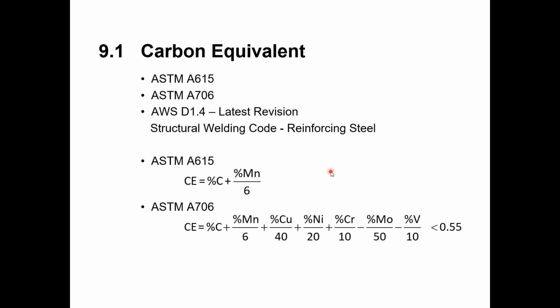All right, let's say you had a carbon equivalent of 0.6, and you were dealing with a number 7 bar. So carbon equivalent of 0.6, number 7 bar. You're in the fourth row down, and you're in the middle. So up to 6 is the first one, 7 to 11 is the second, 14 to 18 is the last. You're a number 7 bar, so you have to preheat to 200 degrees. Now we're starting to see some pretty stringent implications here, that you have to preheat that bar to 200 degrees before you can weld it.